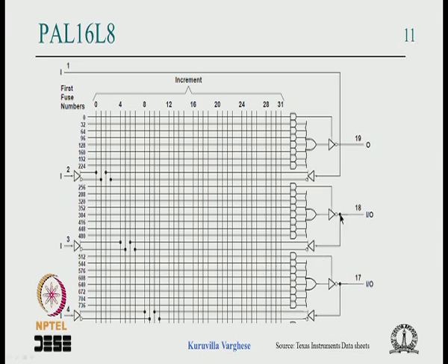Once again, going back, this tells us that this can be used as a feedback, okay. One simple example is that you think of a cross coupled NAND latch. I hope we have discussed this at the beginning, maybe somewhere. So you have 2 NAND gates. The output of one NAND gate drives the input of the other NAND gate. It gets one set input and this gets one reset input. This output is feeding back to the other NAND gate input.